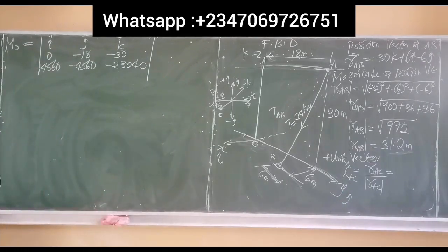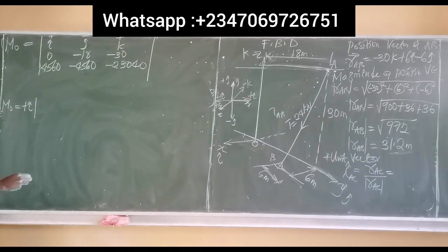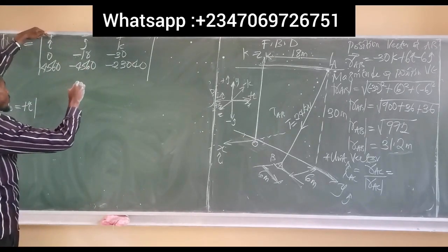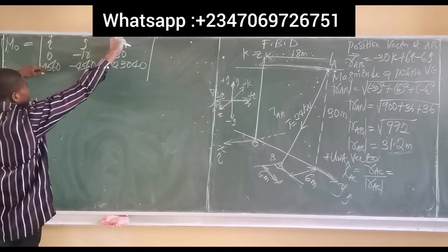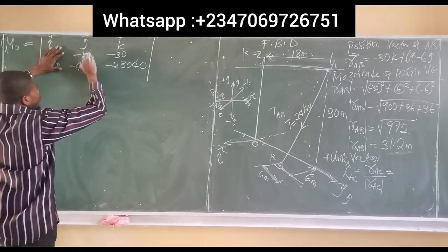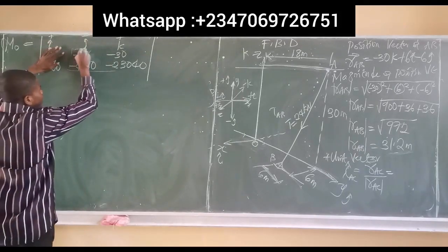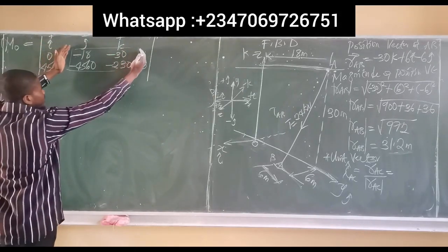All right. So the moment about O now is equal to, remember, when evaluating with matrix, we want to start with the i direction. Remember, this is plus. So always you start with the plus i direction. Then you form your determinant matrix. Since I'm considering the i direction, I'm going to block this row and this column. So I can only see these other two terms.